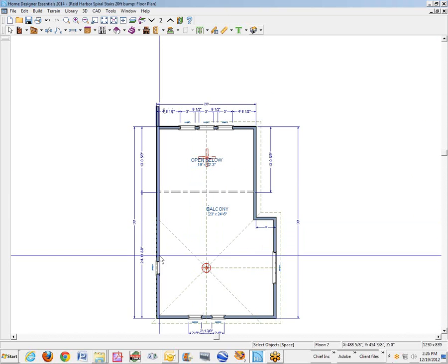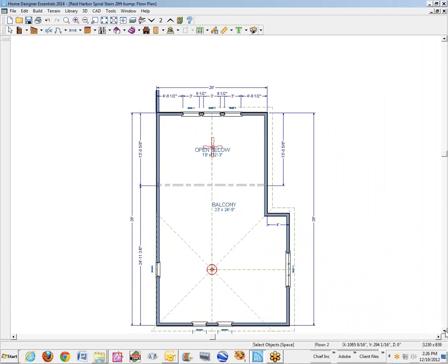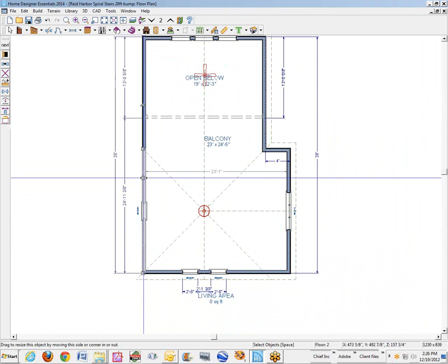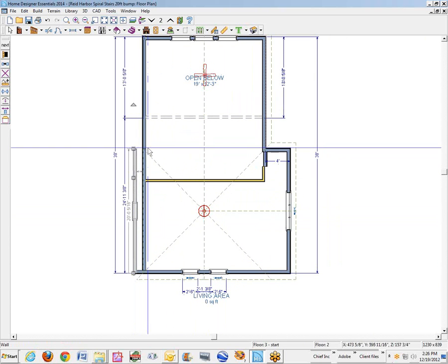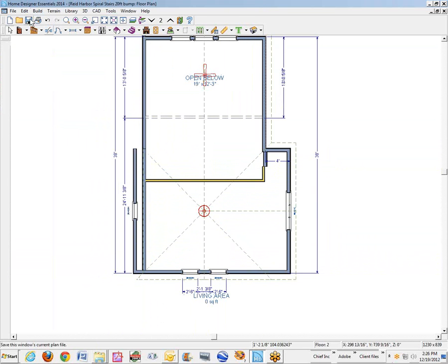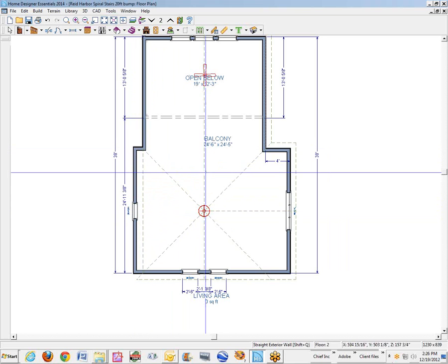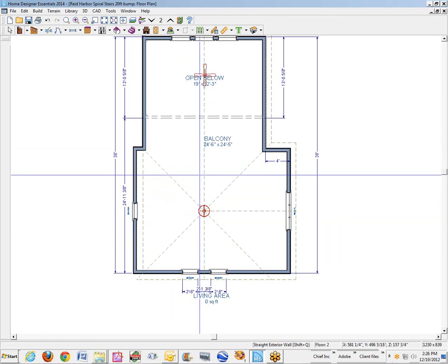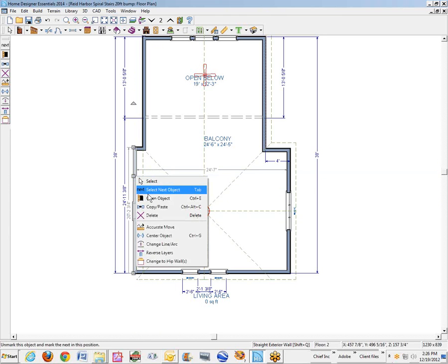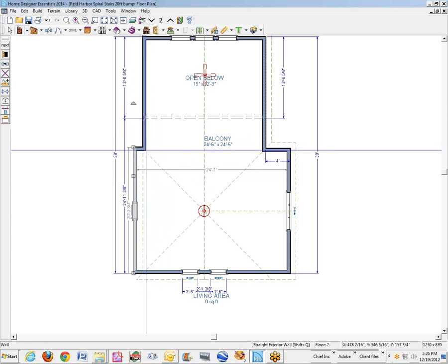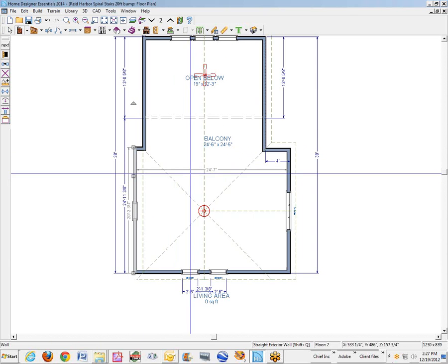And what I did, I hope for this video it will actually repeat exactly what it did before I started the video. But what I did, just on a whim, I decided to pull this wall out, and of course the program automatically fills in with the automatically generated attic walls. I was expecting that. I'm going to draw a wall in here, and of course those automatically generated walls then disappear. Now the programming is still in this wall for a full gable. That hasn't changed. All I did was just kind of help the software out here.